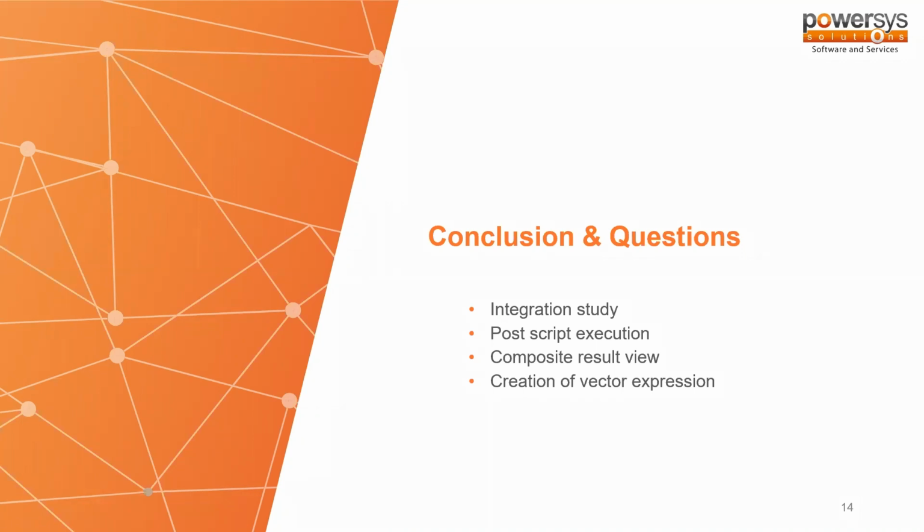As the user pointed out, it's not possible to draw efficiency maps for flux switching machines, and it's not possible in Designer using speed priority either. We don't have a pre-made implementation for those types of machines.